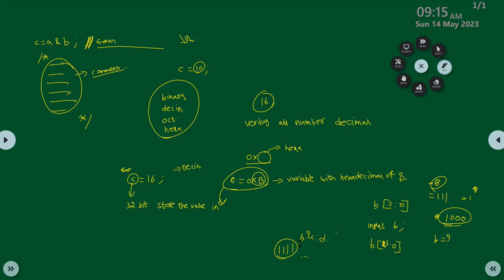So only in that single case is the value of C assigned to A, and for all the remaining cases, D is assigned to A. If you are giving multi-bit input in place of single bit, then the tool considers the bits as a single bit. So it is expecting all ones with the question mark.